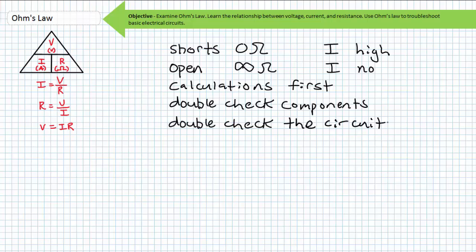Double check the circuit. Make sure it's hooked up as intended. I know it seems dumb, but use colored wires. Number the nodes. Pretend you're current flowing through the circuit. Visualize it. If this stupid trick works, it's not stupid. If you're using a protoboard as your circuit building environment, look at it from all angles, not just the top, when you're troubleshooting connections. Different angles often quickly reveal a missed or off by one connection.